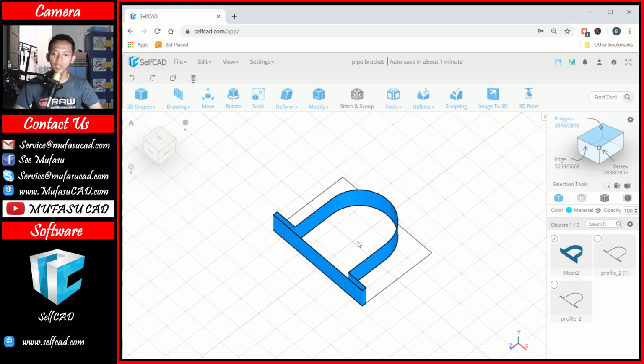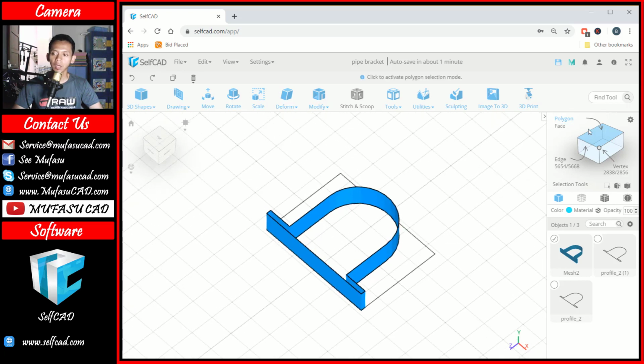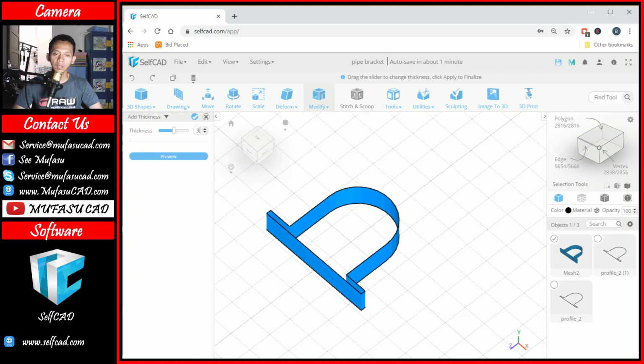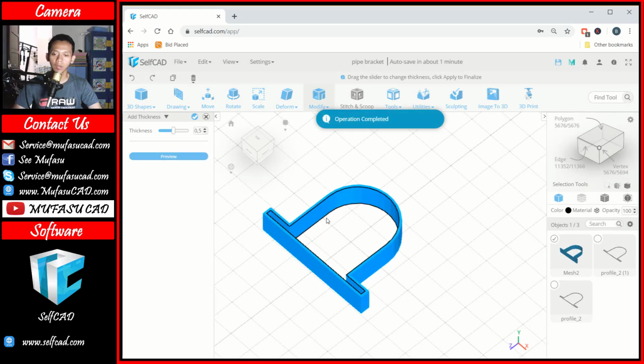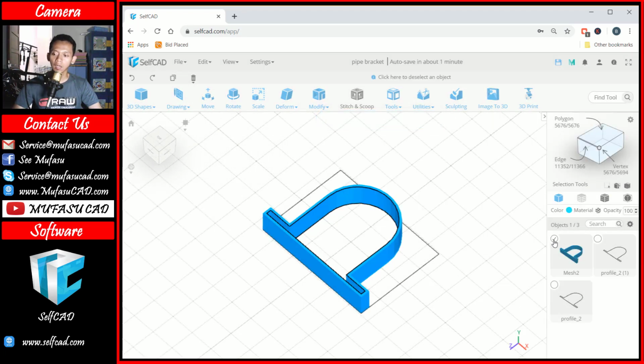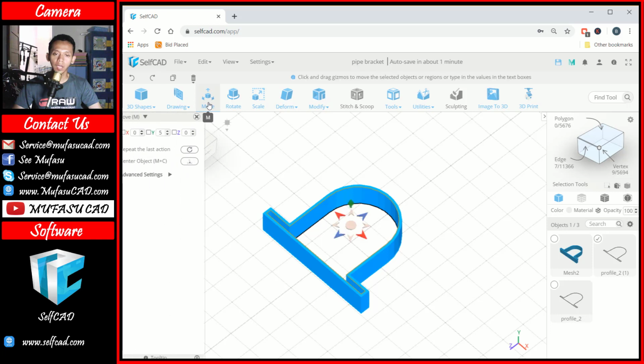And then I will use add thickness on this object. You can uncheck this polygon and we can click this modify and click add thickness. Okay, I will add the thickness with height 0,5 and you can click preview. Okay, this is 0,5 and you can click OK to apply. I will select this object and then you can move to the bottom 1. Okay, you can click the move command and then change in here the y axis into 4.